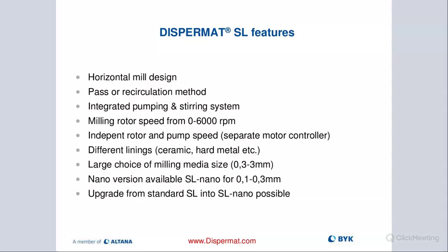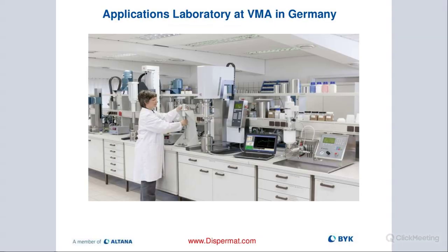You have your seals, you have your O-rings, you have all these wear components that need to be replaced periodically. And also you have the potential for leaking, which is not something that would happen with the basket mill. So there is no leaks there really. So this is only advisable if you want continuous mode and below 500 nanometers, and anything above that or not continuous, I highly recommend take a closer look at the TML basket mill.